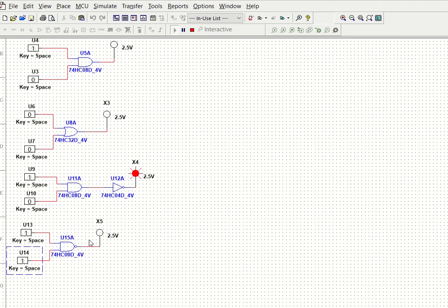Okay, only for 1 1 you can see the light is off, according to our truth table. But if you check the other combinations, your light is always on. This is the case for our NAND gate. So only for the 1 1 combination the light is off. If you take the 1 1 combination here also, these two are basically the connections for our NAND gate. This is not an AND combination, and this one is NAND, directly the NAND circuit. Okay, NAND IC.